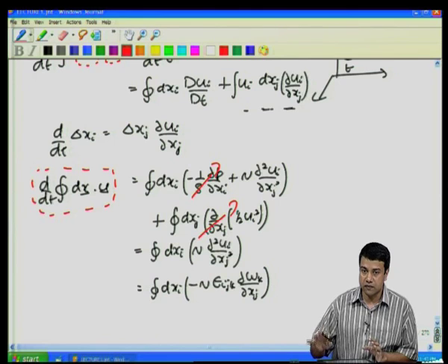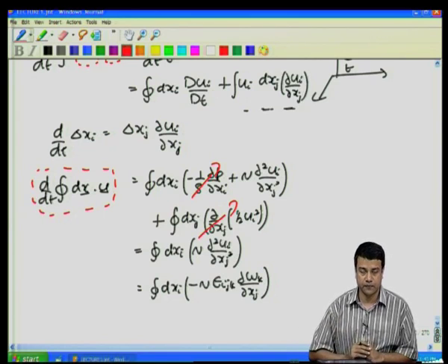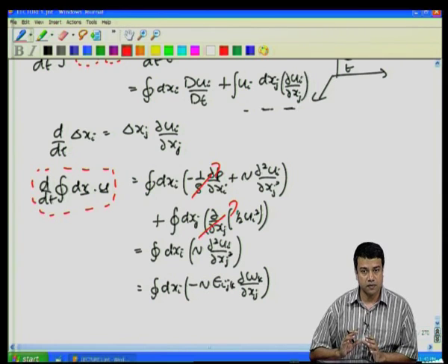So, even in an inviscid fluid, if you do have vorticity, this is telling you that it cannot be generated, it cannot be produced or dissipated in the inviscid fluid, but just moves along in such a way that the circulation remains unchanged in the flow. So, this is about vorticity dynamics within the flow.